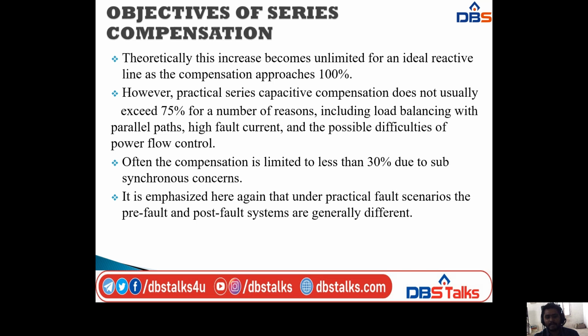However, practical series capacitive compensation does not usually exceed 75% for a number of reasons. Those include load balancing, high fault current, and the possible difficulties of power flow control.